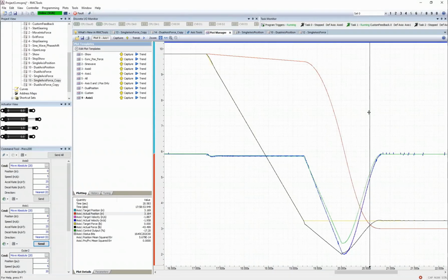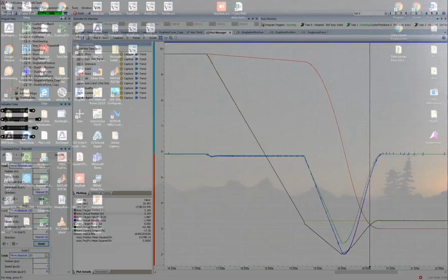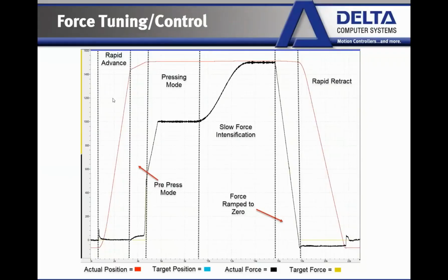We've got a force limit control as well, so you can be in position control. But rather than ever going into force, you can say, I'd like to go to a specific position, but I never want to cross a specific force. We can limit the force. And again, it's just like it sounds, it's limiting that force. And that's another control algorithm that's available as well. If you guys are interested in that, again, reach out. We'll give you some more information on it. Okay, let me jump back to my slideshow. So you can see we're able to achieve our press control here.